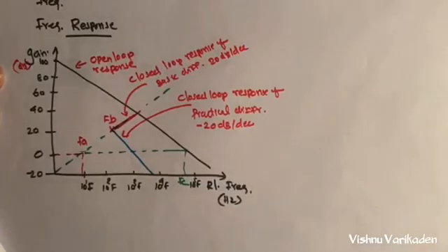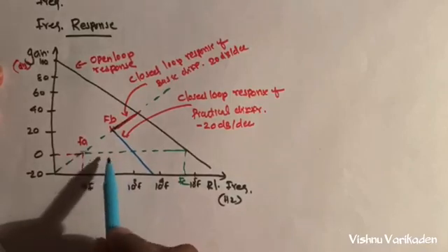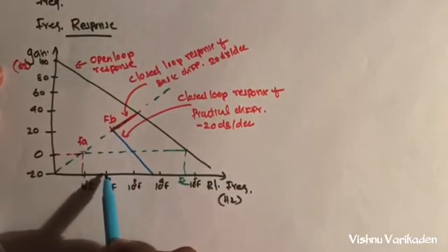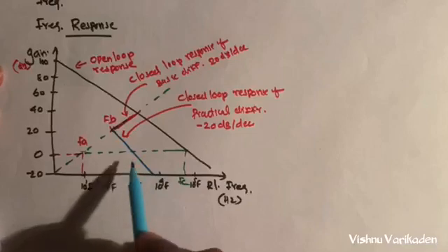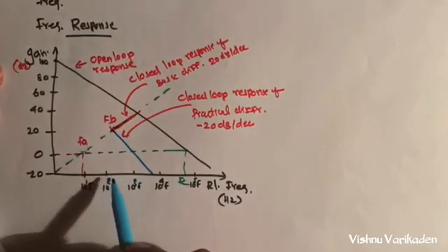From the last equation, Vout(s) by Vin(s) is minus s R F C1 divided by (1 plus s R1 C1) the whole square. This equation shows that the gain increases at 20 dB per decade for a frequency range less than FB, and decreases at a rate of minus 20 dB per decade for F greater than FB.